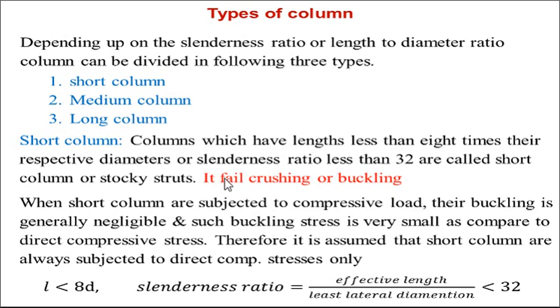Most of the time these short columns fail by crushing. When short columns are subjected to compressive loads, their buckling is generally negligible. Whenever short columns are subjected to compression, the buckling or bending is negligible or of very small value. Sometimes we do not even consider bending in the calculation, because such bending stress is very small as compared to the direct compressive stress. So most of the time short columns are subjected to direct compressive stresses only. Therefore it is assumed that short columns are always subjected to direct compressive stresses.